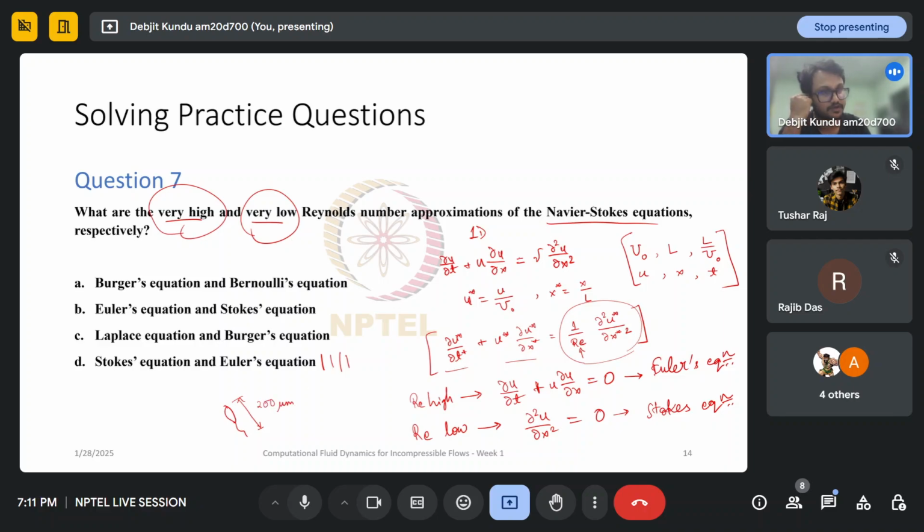It's very, very small. So at that very small scale, the velocities are also very small. The velocities are in something like nanometers per second or maybe a bit larger, not more than that. Maybe in micrometers per second. That's the typical range. So if you calculate the Reynolds number over there, it is like 10 to the power minus 3, 10 to the power minus 6, and so on. Very small numbers. So in that case, you can ignore the inertia altogether. There is no inertia in the system.